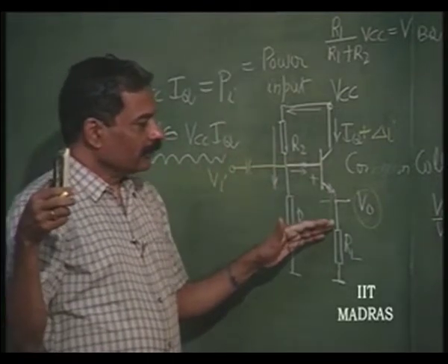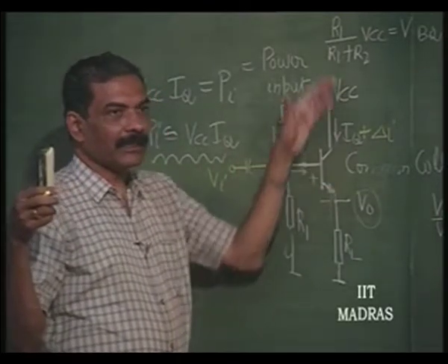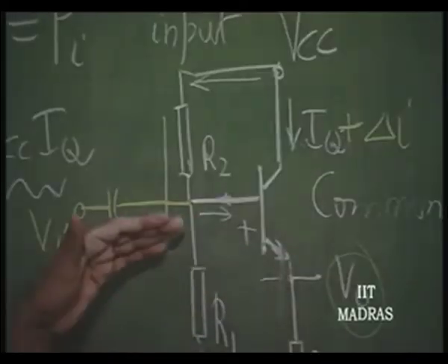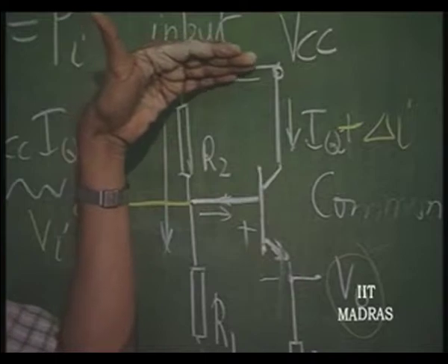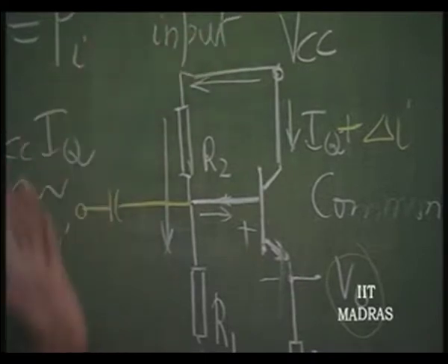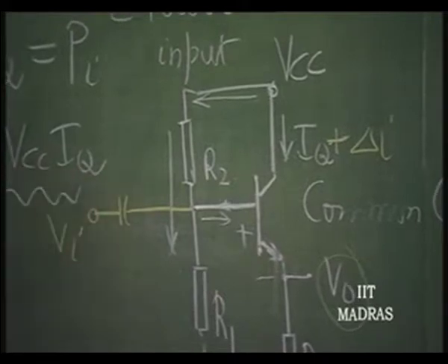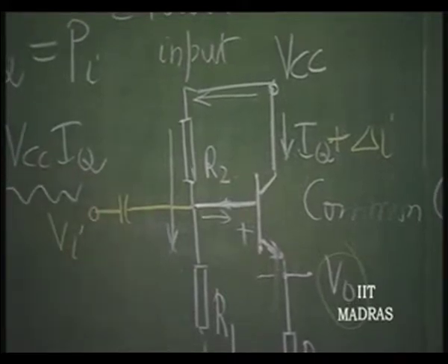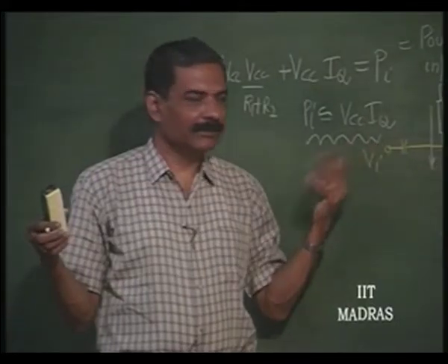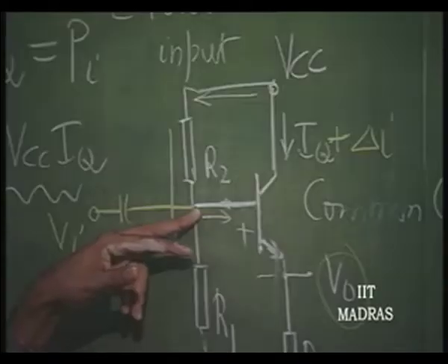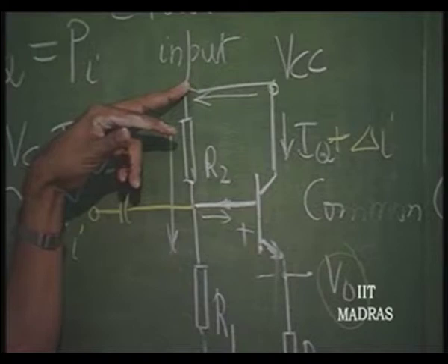Now, what is the maximum current ultimately it will lead to, where Vi becomes maybe almost up to VCC, because this might be coming from the previous stage, and previous stage is also connected to a supply like VCC, and therefore, the maximum voltage you can have there is at most equal to peak voltage VCC. So, this base voltage can go up to VCC.